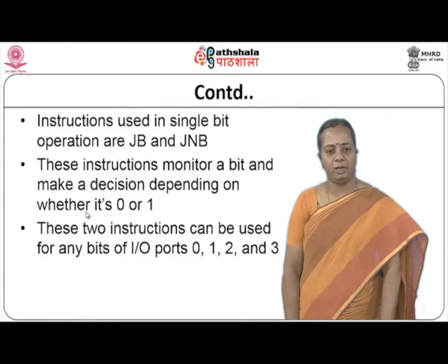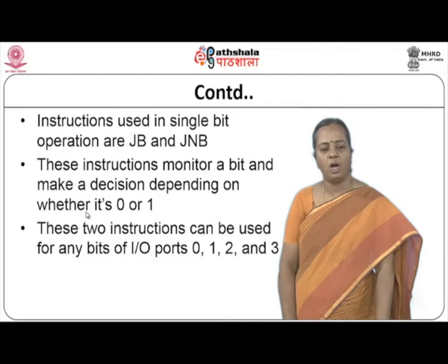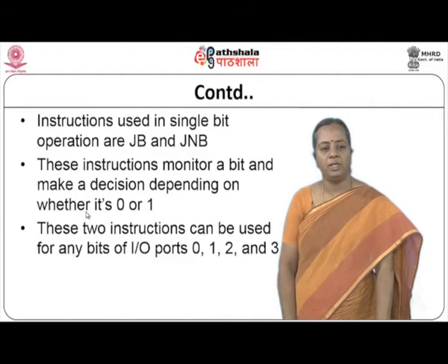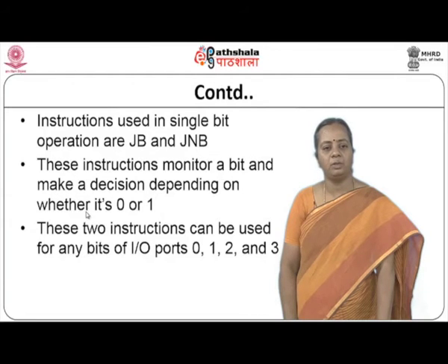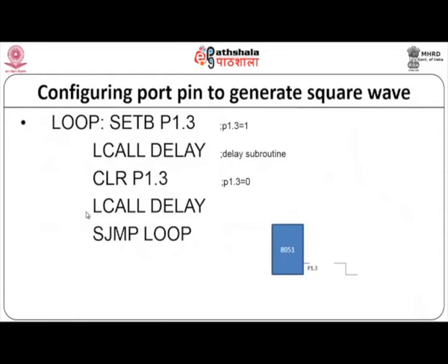Now, we have gone through single bit operations as well as how we access the ports. These instructions are used to monitor a single bit, and based on that we can decide what process to follow if it is equal to 0 or 1. With these ports and pins we can develop applications through the 8051 microcontroller.